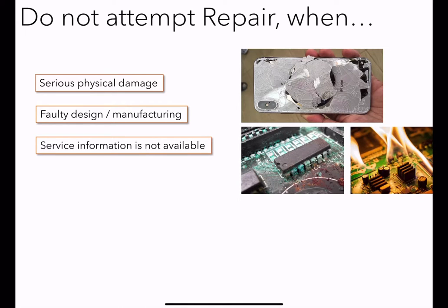Okay, when the devices or the components have been damaged by fire or water damage, in such cases you should not try to repair it. Attempts to repair should not be made, because the better option is just to replace that. If a circuit board or a component has been water damaged or damaged by fire or smoke, we should just replace that. We should just replace the whole section of those components. The attempt of repair may not be very useful.